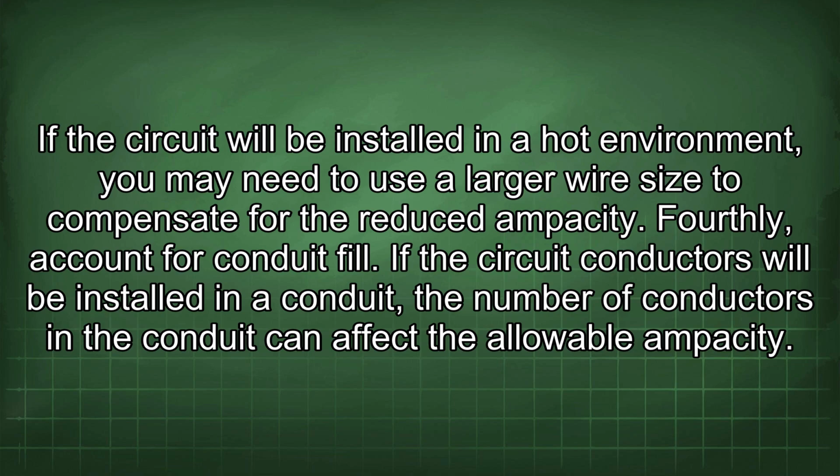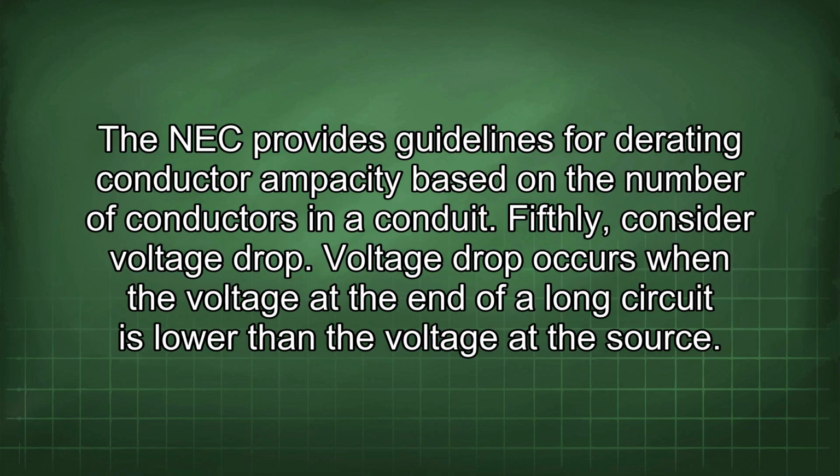Fourthly, account for conduit fill. If the circuit conductors will be installed in a conduit, the number of conductors in the conduit can affect the allowable ampacity. The NEC provides guidelines for derating conductor ampacity based on the number of conductors in a conduit.